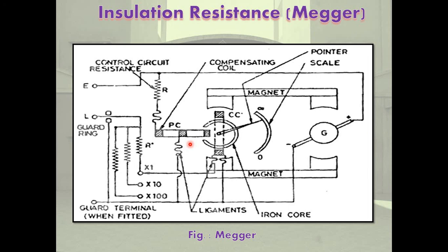The Megger should be cranked at the speed indicated in its certificate, usually 120 rpm, for 60 seconds. After the start of the cranking, the insulation resistance should be read on the Megger scale. The value thus obtained is called the 60 second insulation resistance and is designated R60 or IR60. Or a 10 minute reading is taken for a large transformer.